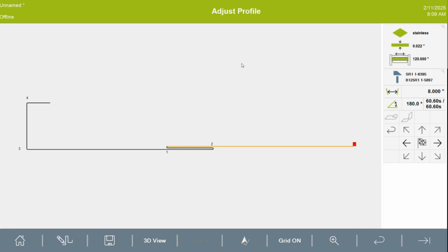But getting around the S-lock as far as horizontally is not a problem. Machine can calculate it. You can bend it. It'll work. Okay. It's nothing special to do. But when you make this part and you press that hem, you have to have, first of all, enough opening for these to fit inside. Okay. You have to leave that part open enough.